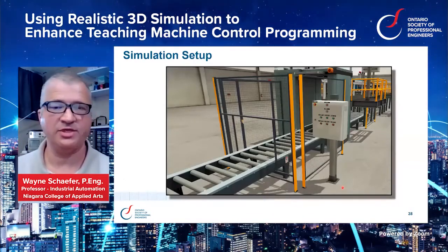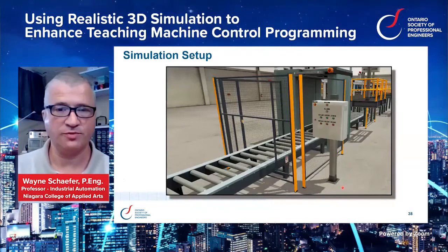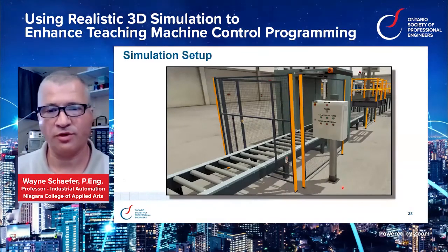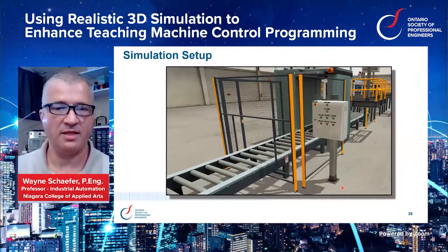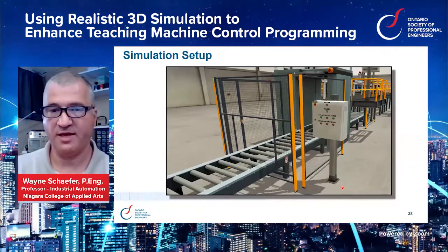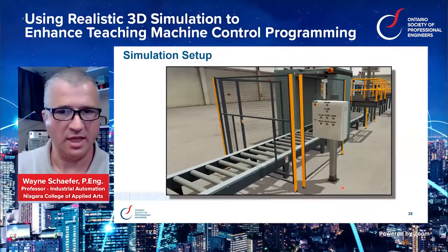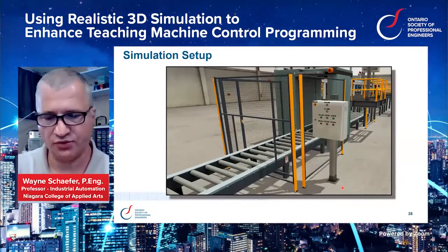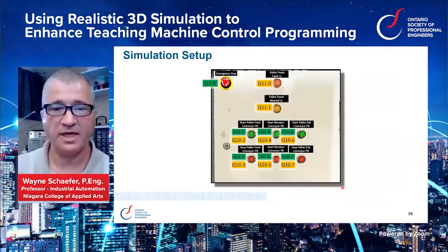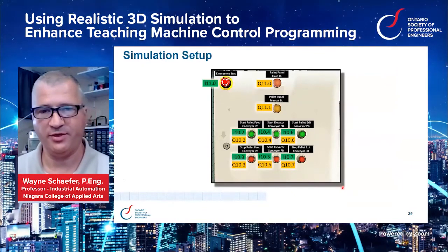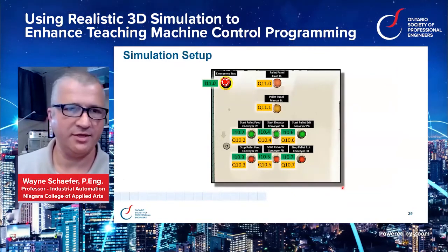So finally, at the pallet entry and exit area, it has its own push button panel again, located at the bottom corner, where it's better to see the pallet conveyor, and the location of these panels is good at being able to highlight that we actually want to be within line of sight of the equipment that we're trying to control. And similarly, the pallet panel has manual control panels and status indicators like the other ones.